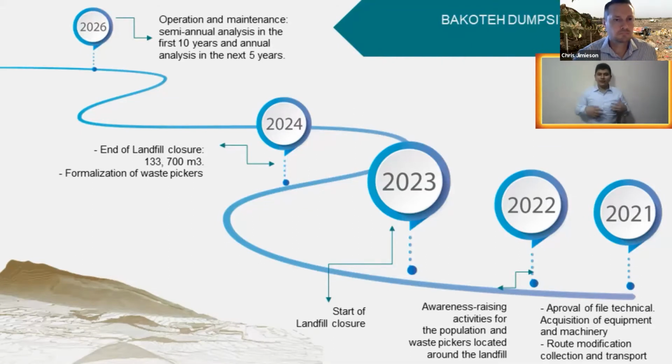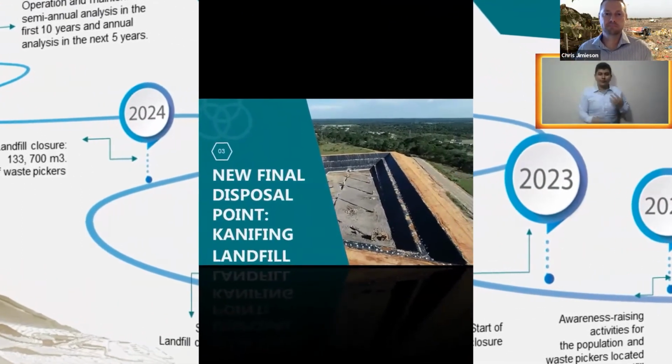In the case of stabilization verification, the conservation of the coverage and the settlements on the landfill surface must be monitored. For the environmental monitoring, reference is made to environmental parameters for which it is necessary to carry out tests and interpret the results to know if acceptable values are achieved and that they do not affect people and the nearby environment. Additionally, you can know when it is suitable to use the place for some other activity. It is worth mentioning that monitoring has been considered for a period of approximately 15 years, this being an approximate time in which waste must have stabilized and not be sources of any health or environmental problems.